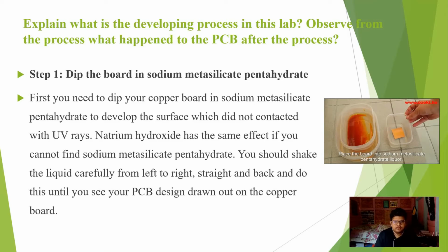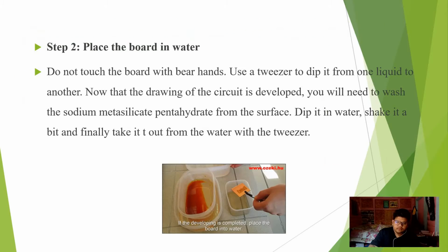Sodium hydroxide has the same effect. If you cannot find sodium metasilicate pentahydrate, you should shake the liquid carefully from left to right, straight and back, and do this until you see the PCB design drawn out on the copper board.